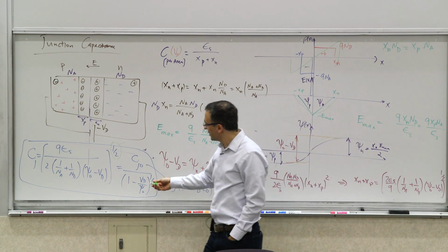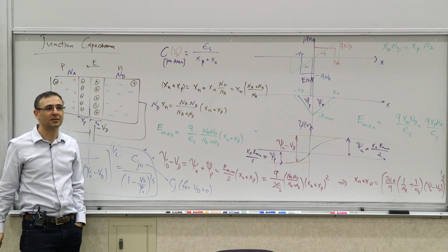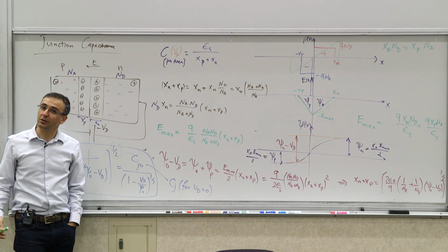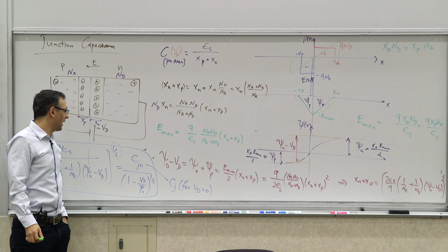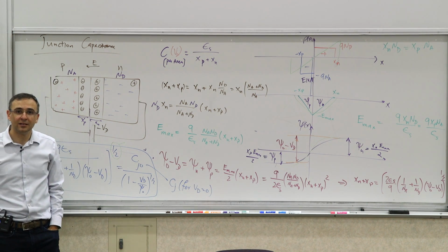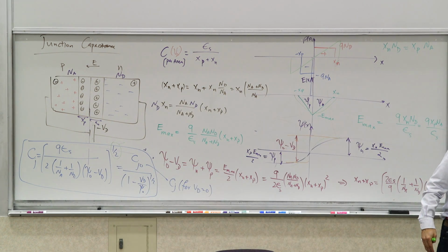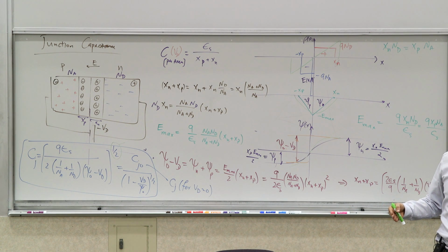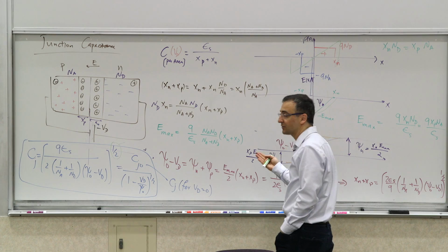This capacitance depends on the voltage across itself. So it's a nonlinear capacitor. Now, it may be a good thing or a bad thing, depending on what you're trying to do. So if you're trying to make something that's very linear, and you introduce a fundamental component into it, you may see harmonics in your electronic devices that may be coming due to this nonlinearity of this capacitance.